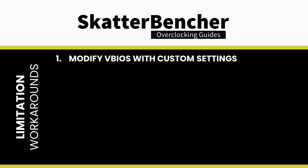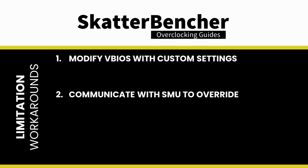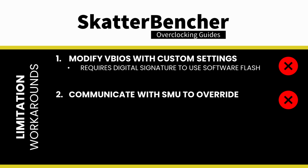If that is the case, there are essentially two ways that we could work around the overclocking limitations. One, modify the VBIOS with a different configuration, or two, communicate directly with the SMU to override the stored information. Unfortunately, neither are a real option. The VBIOS requires a valid digital signature that only AMD can provide.